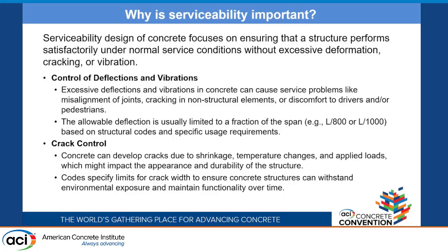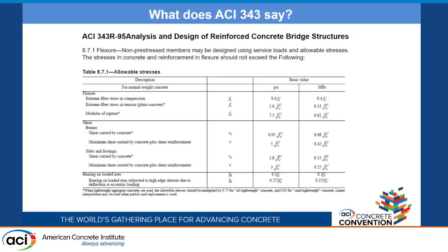We used to look at deflection for that, control for that, and the reality is vibration is much more important than the deflection. And the other thing is crack control. So whether it's a reinforced concrete bridge or a pre-stressed concrete bridge, we want to try to control the cracking in those members. What we do is a little different for each type of bridge. But again, in the interest of time, I'll leave it at that.